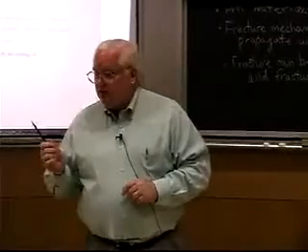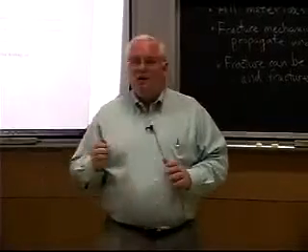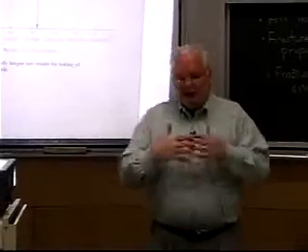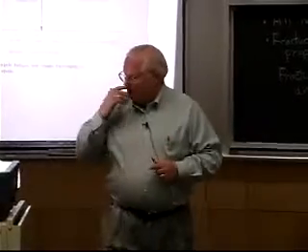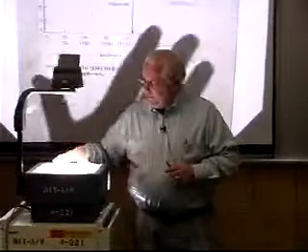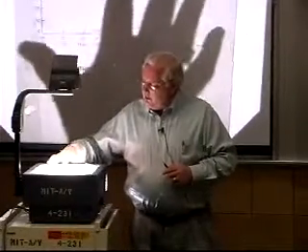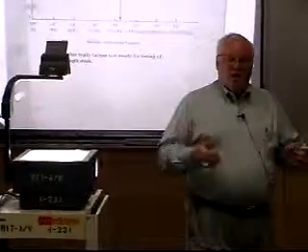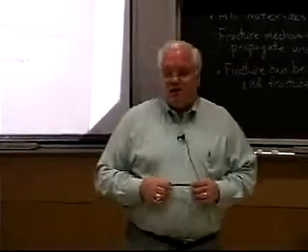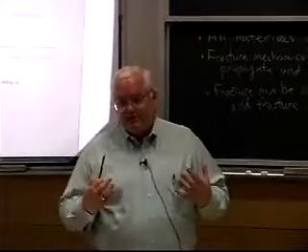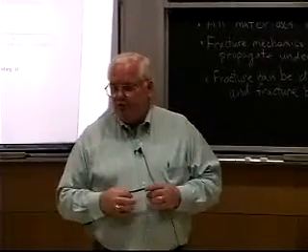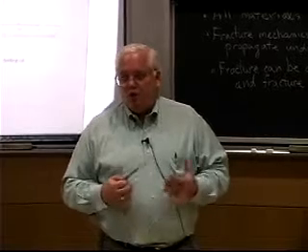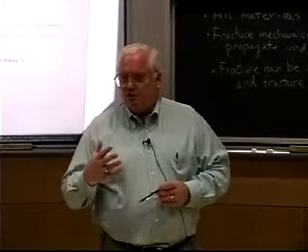Aluminum does not have a fatigue limit. Why? Well, there are lots of reasons, but basically aluminum, being more reactive, gets a little bit of surface damage and it oxidizes. So with aluminum, this curve will still have a very, very slow slope. A number of years ago, they wanted to use aluminum wheels on trucks, because if you can make something lighter, remember, the faster something moves, or the longer you use it, the more important lightweight is.